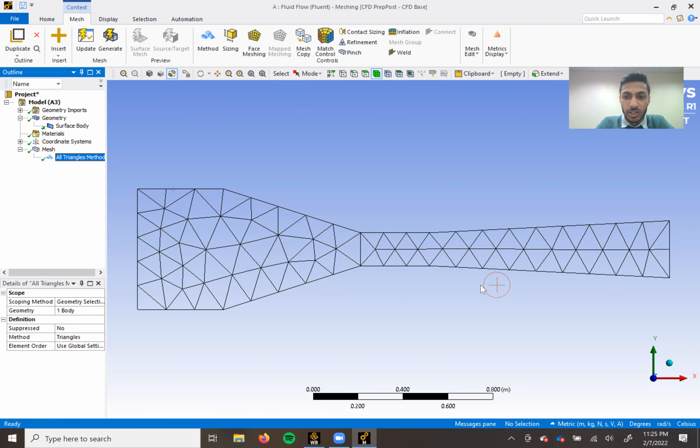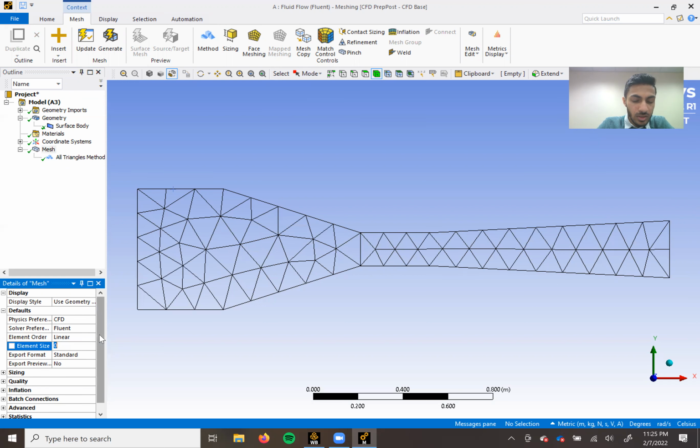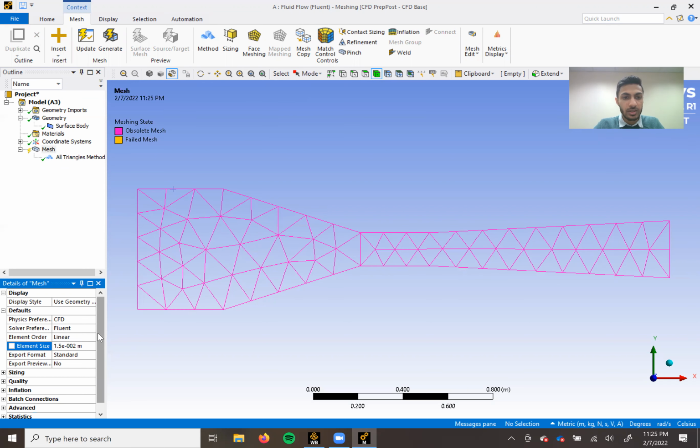So you can see this is what it generates here. These are very large meshes compared to what we wanted to calculate. So we're going to have to make these meshes smaller. When you're actually doing simulations, you want these meshes to be as small as possible while still being feasibly run in a timely manner. For the purposes of this video, I'm not going to go super small with it. I'll probably go 0.015, something like that. Hit enter and generate that. We'll see what that looks like.